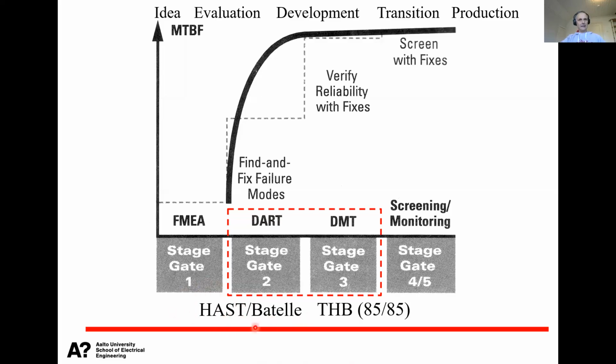There's the battle test. This is just one corrosion test. Here we include humidity and impurities, and the point is the same: we want to check how well our design withstands it, how well our corrosion protection is made. Of course, this corrosion test can also be used to estimate lifetime.